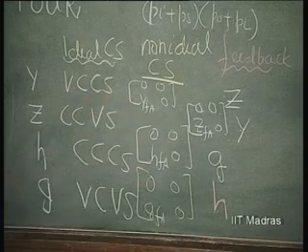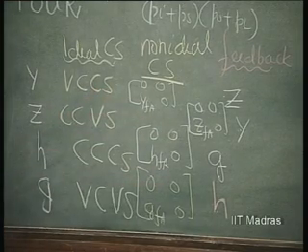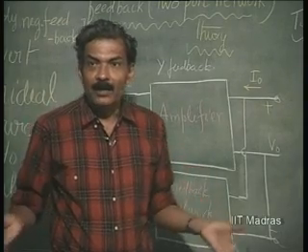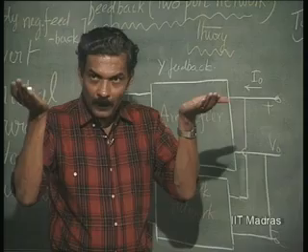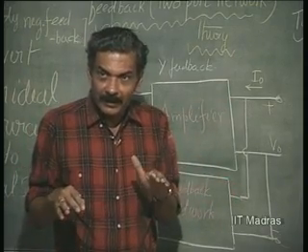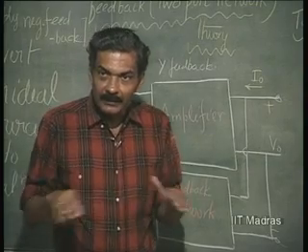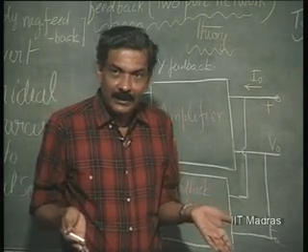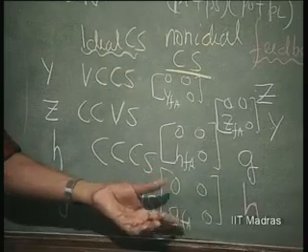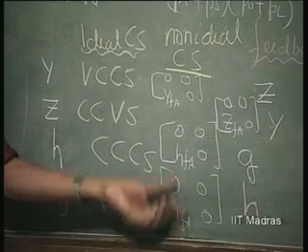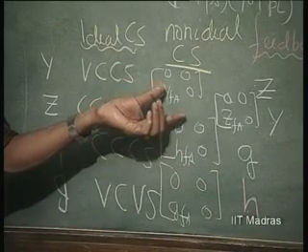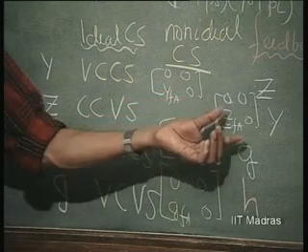In all these things, since the forward transfer parameter is desensitized with respect to the active parameter, naturally the bandwidth also is going up. Desensitization simply means desensitization with respect to everything: temperature, time, frequency, everything. So even with respect to frequency it is insensitive, or its bandwidth is improved. Corresponding to this, the bandwidth of GF is improved. Corresponding to this, the bandwidth of HF is improved. Corresponding to this, bandwidth of YF is improved. Corresponding to this, bandwidth of ZF is improved.